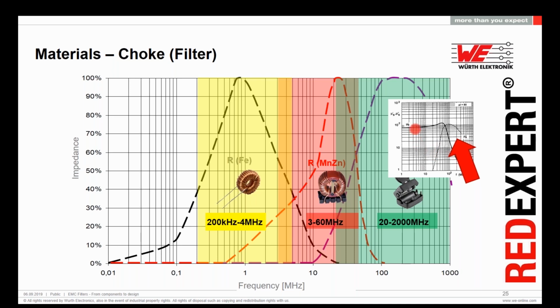In the case of chokes, the power or the data signal is usually in this frequency range, and we are using the common mode choke for filtering in this frequency range. So our differential signal, due to the field compensation, could be anywhere because we have almost no effect of the core. Remember, we have no inductance, while we try to have as many losses as possible for the common mode. And this is mainly the secret. This is why we are taking a look at the losses and not at the inductance or the capacity to conduct the flux of our cores. And this is why the guys building common mode chokes are taking basically the core materials that the guys from power don't want to use, because for us, the higher the losses, the better.